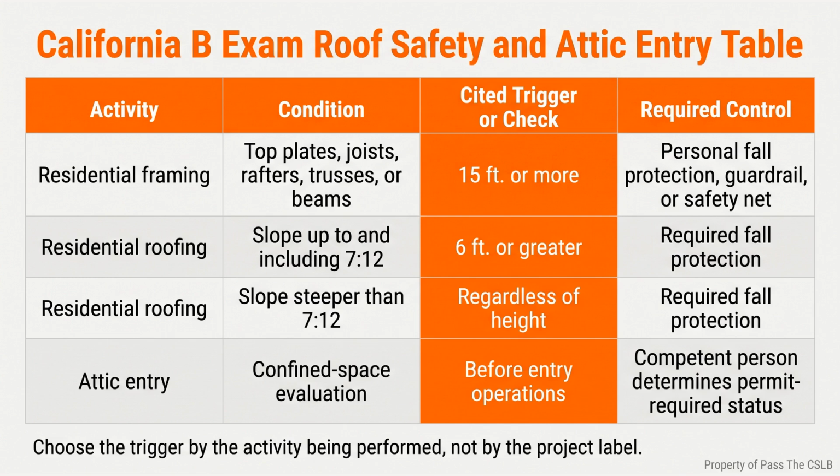For a vented assembly, I verify the required net-free area, the distribution of upper and lower vents when the reduced ratio is used, the protected opening size, the 1-inch clear path at eaves, and the continuity of the channel past insulation and blocking. For an unvented assembly, I verify the insulation type, direct contact where required, vapor and thermal controls, climate zone conditions, and the approved project details.